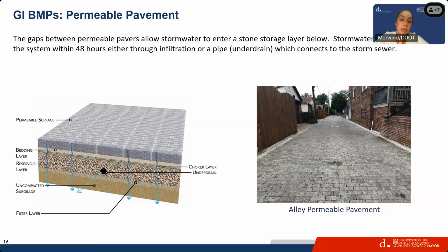One was, why didn't you use permeable pavement parking lanes or permeable alleys in this project? There's a reason. Broad Branch and Spring Valley both have groundwater very close to the surface. So many of the alleys that we primarily selected for this project had to be removed because we can't excavate that deep for the green alleys. The same goes for permeable pavement parking lanes. The only thing I want to mention is that bioretention achieves much more treatment volume compared to permeable pavement. To reach the goals, I might need to propose 6 or 7 permeable parking lanes to achieve the same as bioretention. Next slide, please.